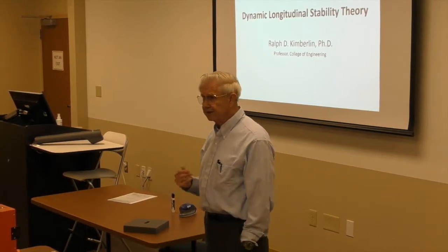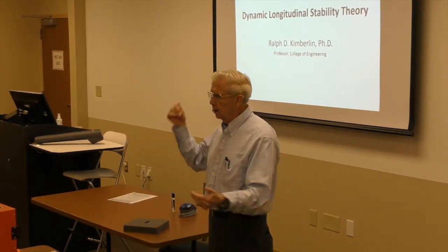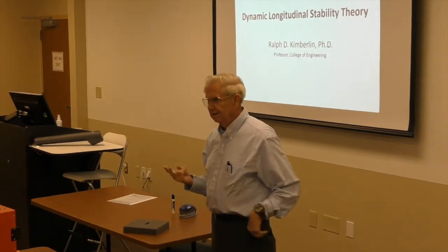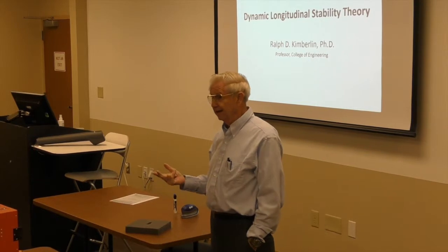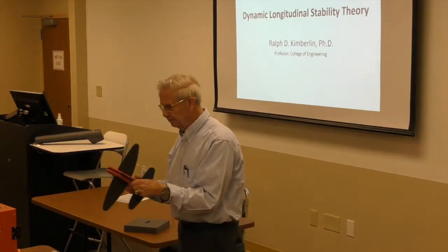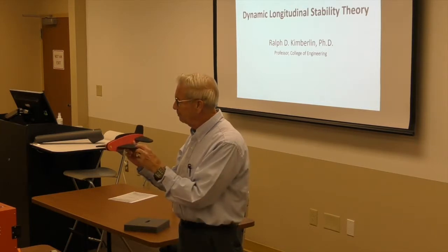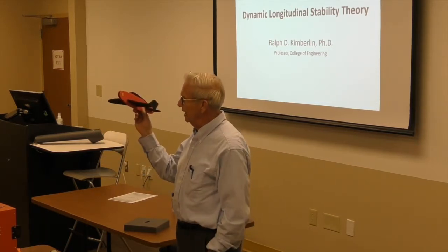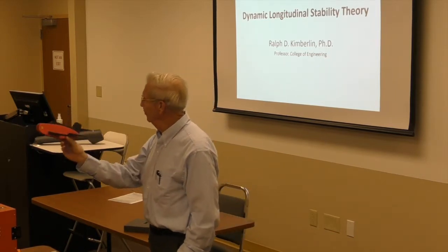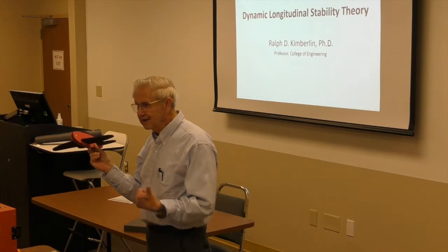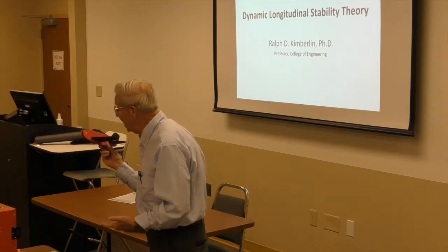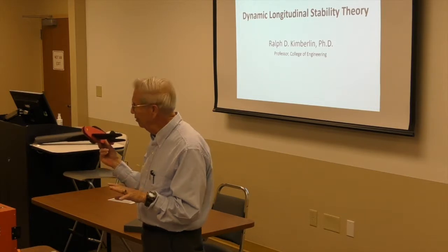Let's look at another case. In this case, we have positive static stability and we displace it and we just let go and it goes right back to trim. Doesn't oscillate or do any of that, just goes right back to trim. Positive static and dynamic in that case, right? Then we'll use this airplane here. Then we take it and we displace it, and it's real happy there. Over time, it just stays wherever we displaced it to. In this case, it has neutral dynamic and neutral static, right? So there's 3 cases that we can have with an airplane.